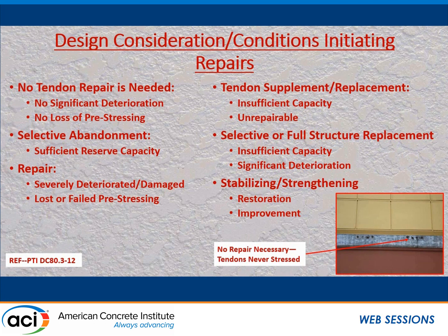Sometimes the damage is severe and you've lost the post-tensioning or the pre-stressing, you've lost the cable, then you have to really look at what kind of repairs and supplements are needed. You're either going to extract a cable and reintroduce it, you may go in and do a coupling, or in some cases there's going to be some sort of additional external reinforcement, maybe external post-tensioning. And in the case of some structures, like the one we had in Seattle, they tore the doggone thing down. Right, wrong, or indifferent, that's what they did.